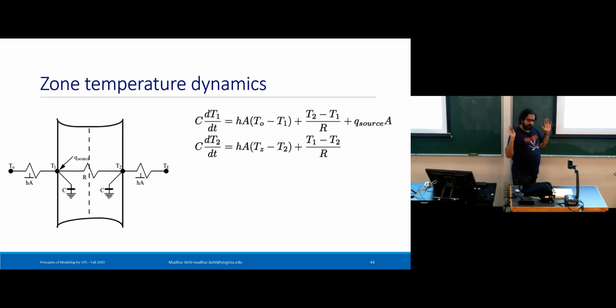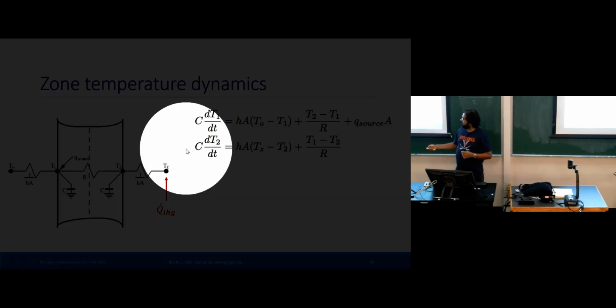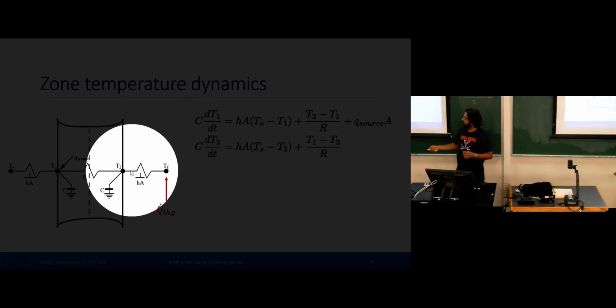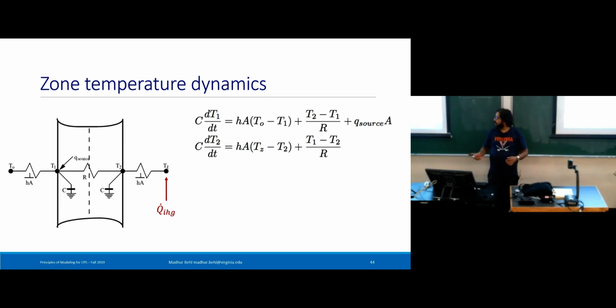And so the total volume of the air in this zone also has some capacity or thermal mass. And that's what we will leverage to treat Tz as also a state. So it'll become clear with this picture. I can first of all say that if I now look at the zone temperature node, so I'm focusing on just this part of the model, we've already established there's a convective heat transfer to the internal surface of this thought experiment wall. But another thing which we have previously discussed, not mathematically but qualitatively, is that the internal heat gain from occupants also changes the zone air temperature, right?